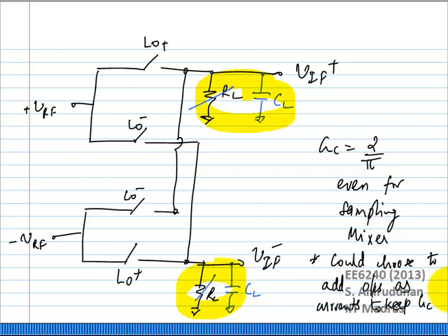Okay. So for example, instead of looking at the voltage here, you could put in a common source amplifier and then add the two currents. So then it is no longer a differential case, it's a pseudo differential case. Okay, and you could choose to add them as currents. So far the passive mixer looks quite good, right? And you will find that this is increasingly being used in receivers. You were isolating the transformer in the whole. Correct, that's right.